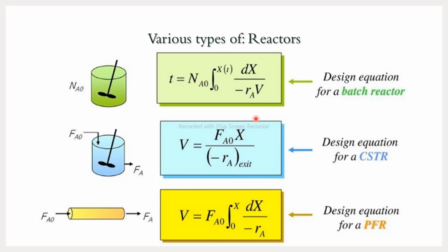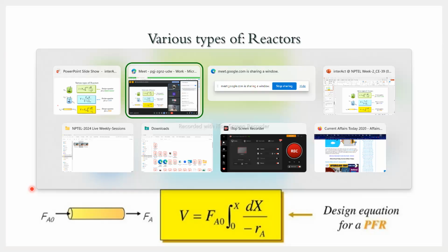If you solve for the percentage conversion, from 0 to Xt, let's say it is converting 30%. Depending on the order, for some cases of the reaction rate kinetics, CSTR will be preferable. It will give more yield than the PFR. In some cases, PFR will give you more yield than the CSTR, if you consider volume-wise, for the same yield.